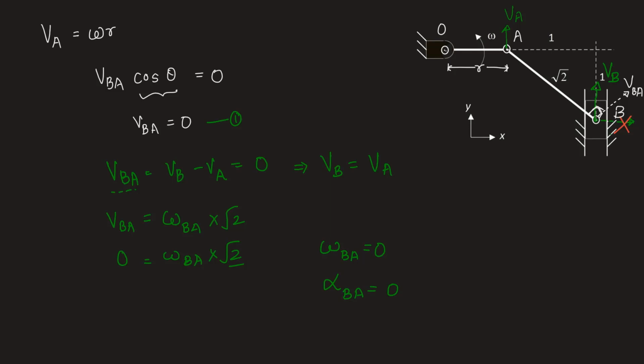So if we draw the acceleration diagram from point O, radial acceleration at point A can be denoted as r omega square. So we'll direct this way because this is the direction of radial acceleration when the crank rotates. So this is r omega square, which is the radial component of acceleration. Also, we can denote acceleration of point B like this, directed upwards in the y direction. The direction is actually same as the velocity at point B. So velocity at point B is directed in y direction. Acceleration will also be directed in y direction. This is AB. This is the acceleration that we need to find.